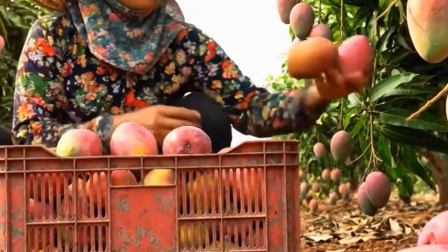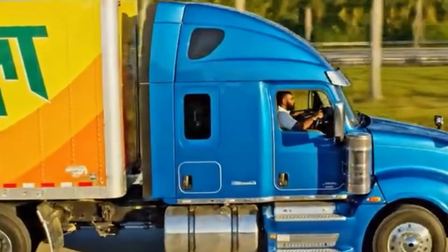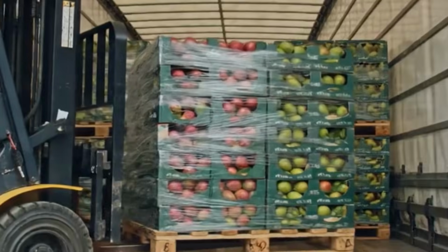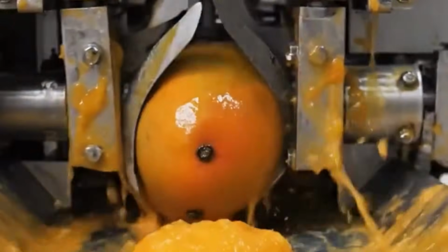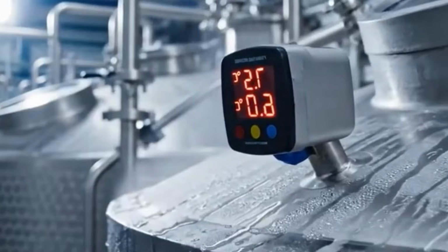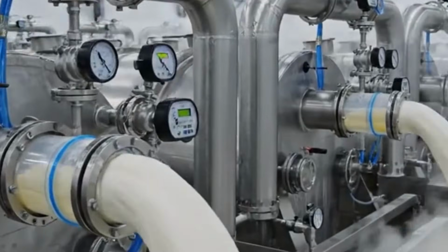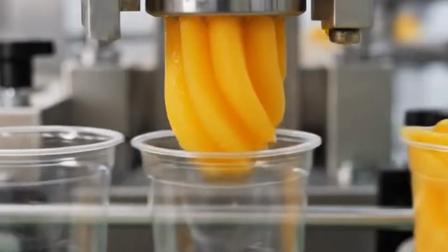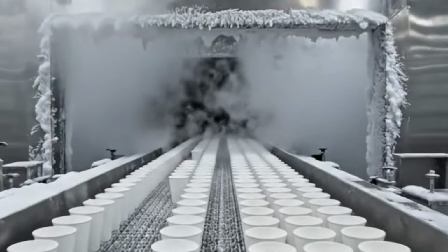The factory production of sorbet begins with the precise formulation of a base mix that typically consists of filtered water, fruit puree or juice concentrates, a combination of sugars, stabilizers, and acidulants. These ingredients are sourced in bulk and stored in isolated silos, refrigerated tanks, or powder silos based on their form and storage requirements. Before batching begins, each raw material is passed through automated intake stations where flow rate, weight, or volume is measured using mass flow meters or load cells to ensure formulation precision to the second decimal.